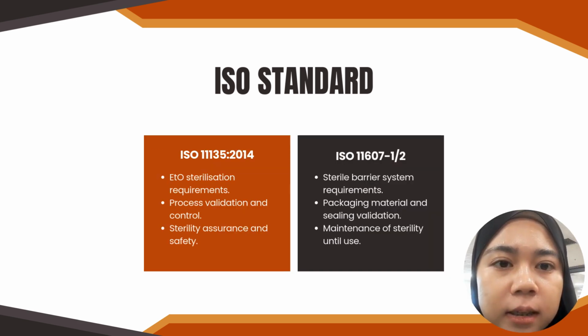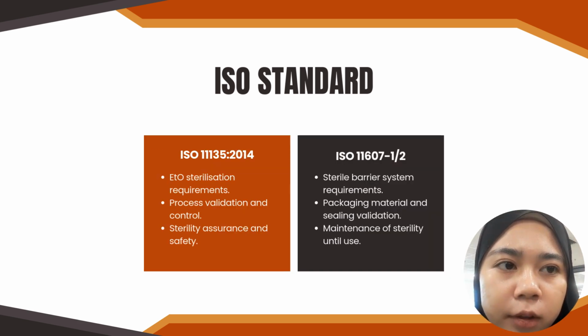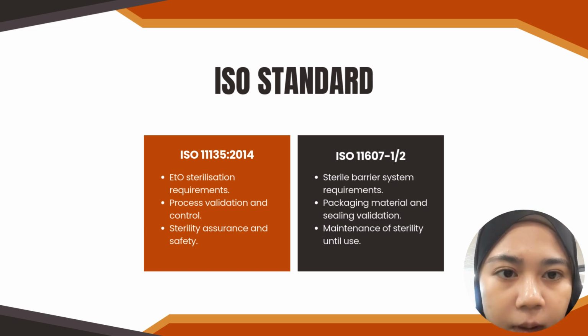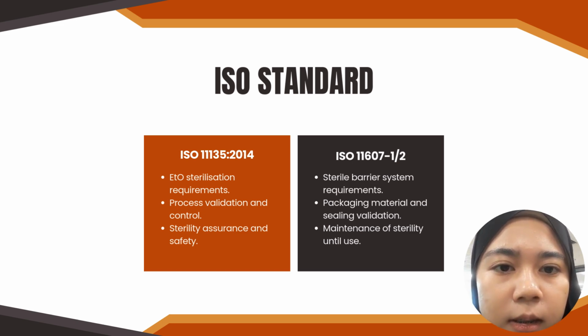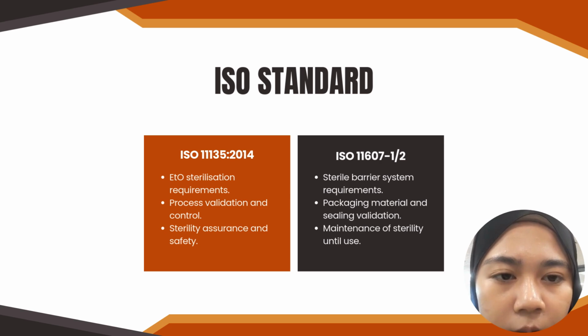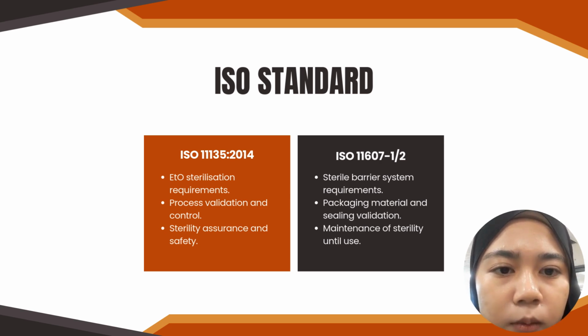So next is ISO 11135:2014, which is for the ethylene oxide sterilization process. So ISO 11135 regulates the use of ethylene oxide for sterilizing medical devices. The standard specifies requirements for developing, validating, and routinely controlling the ethylene oxide sterilization process. Critical parameters such as temperature, humidity, pressure, gas concentration, and exposure time must be monitored continuously. Compliance with this standard ensures effective sterilization while maintaining safety for both workers and patients.